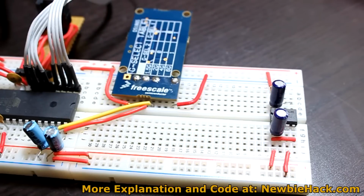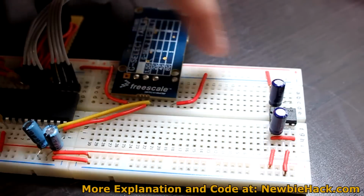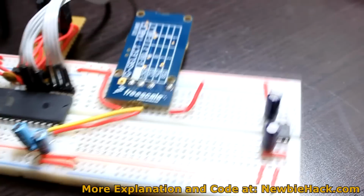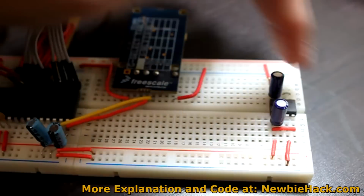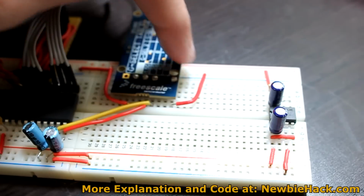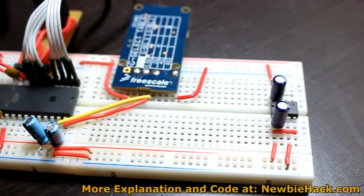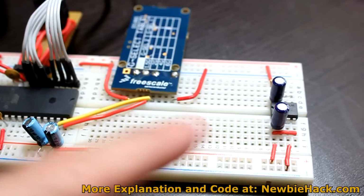As previously, the accelerometer is connected to the 3.3 volt rail here. The ground is connected together all around the board, and we have the small power regulator for the 3.3 volt output here, and the input is 5 volts on this side. If you have questions regarding the circuit that we've created here, please refer back to the initial accelerometer video where we put this circuit together.